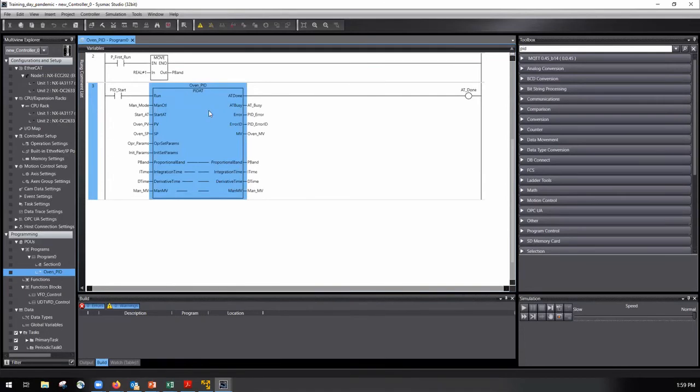Prior to working with Omron's PID loops, I never touched auto tuning PID loops. They were just overly complicated, I found. And I was kind of a do-it-yourselfer, so I always tuned them manually. But I quite like Omron's auto tuning capabilities. And we only have an auto tuning PID function block. So it's there, you may as well use it.